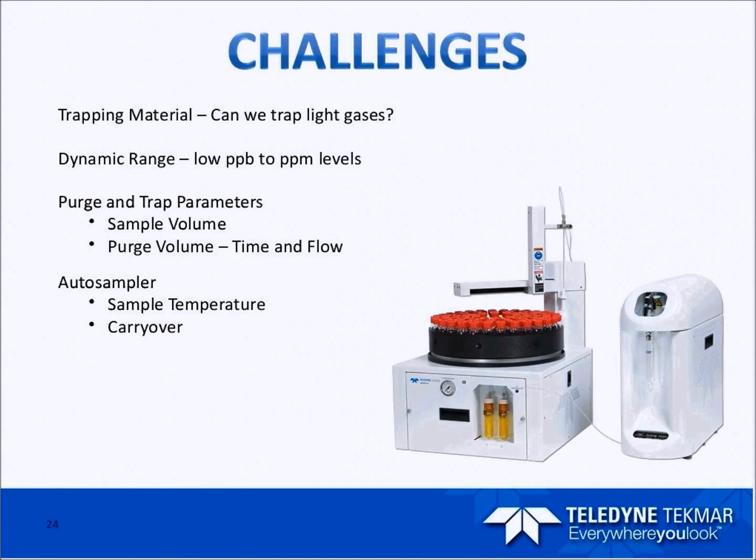It's just all over the board, and you're not going to get the same thing twice. So that was something that we found out the hard way when we first ran it and didn't have the recirculating bath hooked up. It didn't give us consistent results, and we were scratching our heads wondering if it was the trap or something else. But it turned out to be the sample temperature that was really one of the key things for reproducibility. And then when you have an auto sampler, you have potential for carryover, so that was something we had to look into.